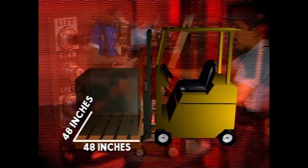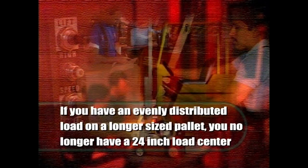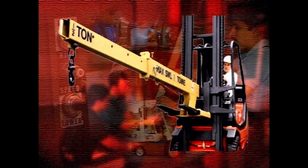The load center of a forklift is the distance measured from the center of the load to the vertical face of the forks. If you have a pallet that is 48 inches by 48 inches, and you have an evenly distributed load on this size pallet, you have a 24-inch load center. If you have an evenly distributed load on a longer-sized pallet, you no longer have a 24-inch load center. If you use attachments extending the load center, obviously the lifting capacity of the forklift can be seriously diminished.